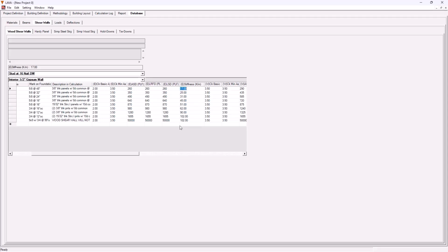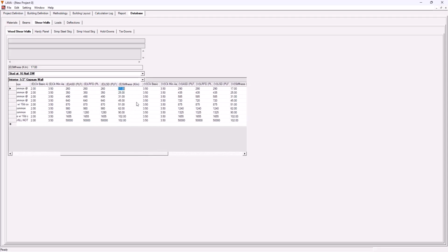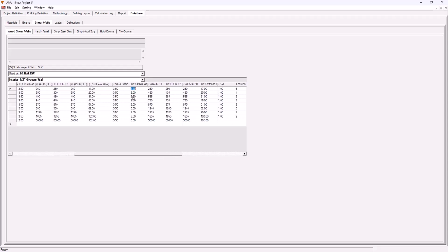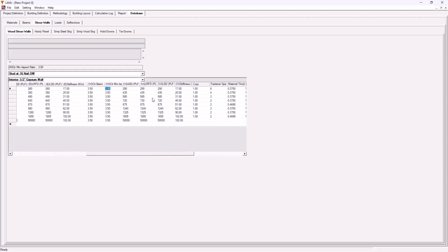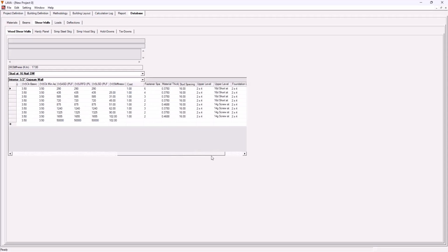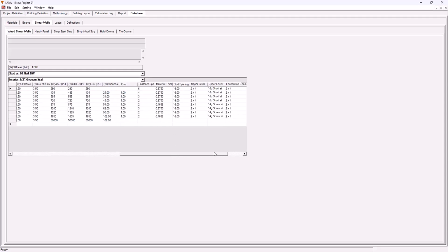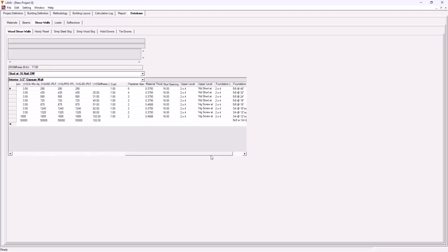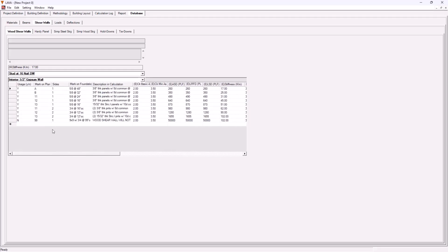So you've got all of these values for earthquake, and these two values here for earthquake, as well as when you look here in the wind. The aspect ratio information is listed here, but usually we're not going to adjust that check. We could also adjust the wind: we have a wind capacity for ASD and the stiffness for ASD. The rest of this information is going to be shown on our plan, and you'll see that described further. So you want to go in and adjust all of these values to match your system, whatever system you are using.